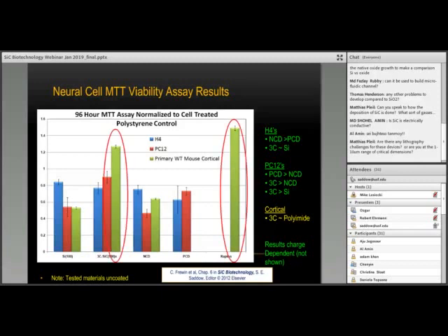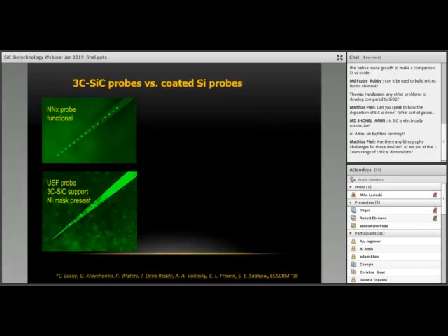So how do we micromachine them? The same methods that we use for silicon, deep reactive ion etching, and so on. I see there's a question about lithography challenges for the DNA sensors. I'll talk about that later. Here we see an example: the top image is a NeuroNexus functional probe, I believe the 16 electrode probe. And here we see just our physical shank. It's not a functional device, with a nickel mask that we use to etch through.